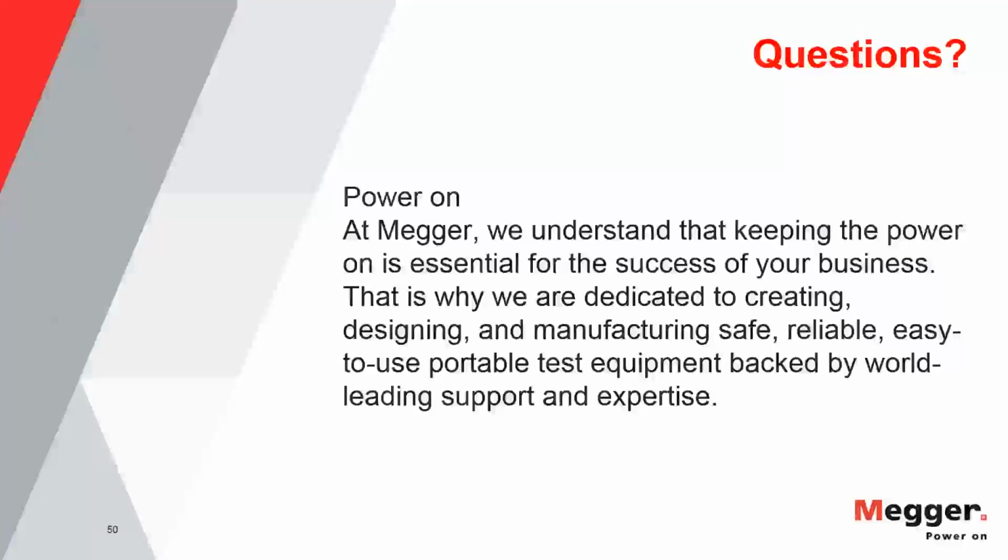And that is typically specific to substation equipment. So you can do PD analysis and to a certain extent PD localization, for instance, on switchgear, high voltage or medium voltage end terminations when it's coming into the substation. Transformers, like your high value assets, are typically targeted with online and in substation handheld applications.